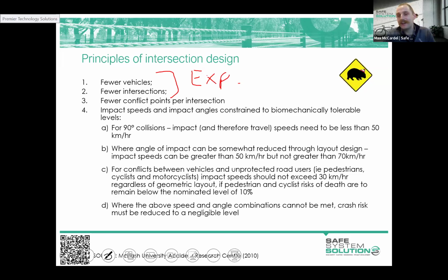Basically, what this is saying is if you're able to influence the number of traffic lanes, that would then reduce the number of conflict points at the intersection. So simplifying the intersection there to reduce the likelihood of trauma occurring there. And that one would be referencing the likelihood. So if you've got fewer conflict points, it's less likely for that collision to be occurring.